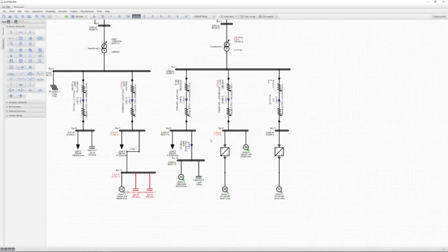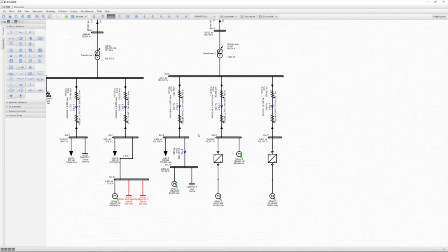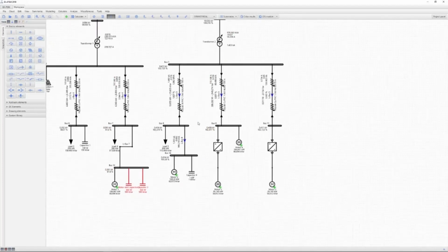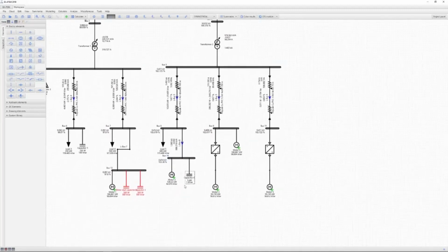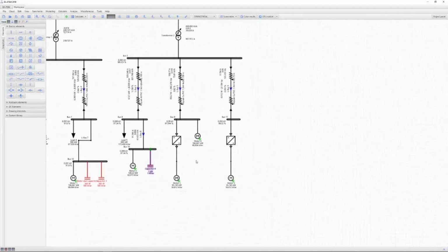And as we can see, the voltage drops are not that bad anymore. And basically we have compensated all the reactive power in the bus bar. So this is another motor start capacitor, and as you can see, the same problem will arise when I'm going to do power flow calculations. Well, maybe not in all situations, but usually this should be turned off because it generates reactive power that usually industry pays for.